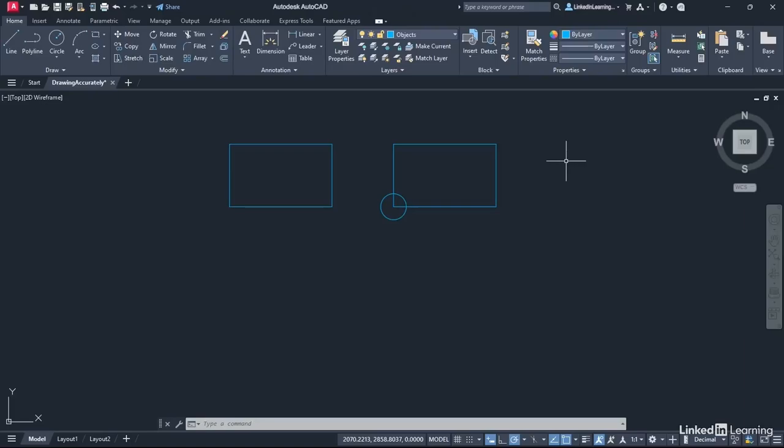Now, I suggest you go and look into coordinates in AutoCAD because there's not just regular Cartesian coordinates like that. You can have angular settings for relative coordinates as well. So you can put an angle as well as a distance and things like that in place as well. Go and check out coordinates in the AutoCAD help screens. It's worth a look and investigate them, and then you'll get an idea of how AutoCAD ticks and how the little motor behind AutoCAD calculates all this stuff that you're putting on the screen.